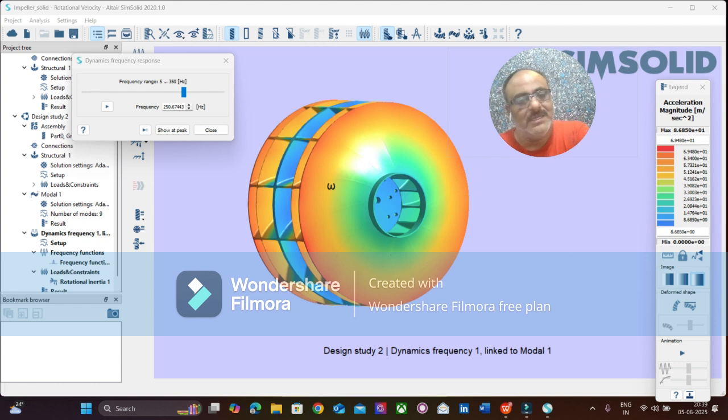Similarly, here there are going to be some shock loads, or some kind of additional loads which are going to be generated, because we have given a pulse to check what is the kind of G force it is experiencing. Now we also need to find out whether the impeller is going to sustain that particular G force. Here in this case it is almost about 6.5 to 7 G. Now this impeller is supposed to be sustaining that 7 G.